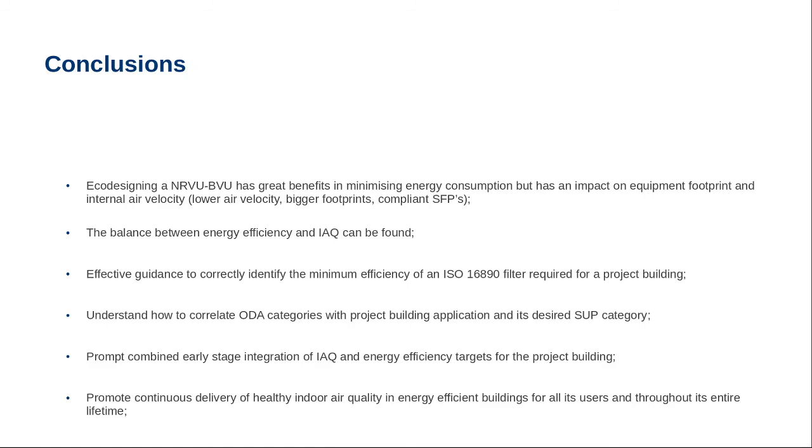How efficient must a filter be to offset enough dry pollutants that will satisfy a supply air quality category? The new ISO 16890 filter classification for general ventilation tells us the whole story. If I refer to an ePM2.5 filter at 65%, I know that such media is 65% efficient at filtering PM2.5 particles out of the airstream. This might be sufficient to satisfy a sub-3 category.